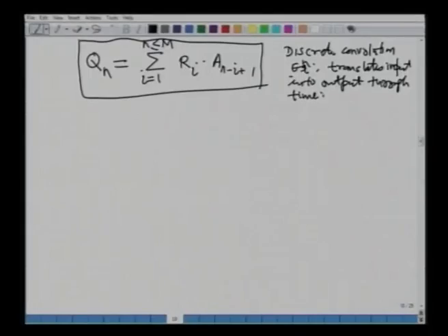We take the topographic map, we estimate the approximate travel times, and then we draw the isochrones using our knowledge of contouring, and we can have any delta t, any desirable contour interval, and then let us say we have the capital I or A1, A2, A3 up to capital I. Then q is something which we want to find out, which is the DRH ordinate. So, using this equation, how can we do that?